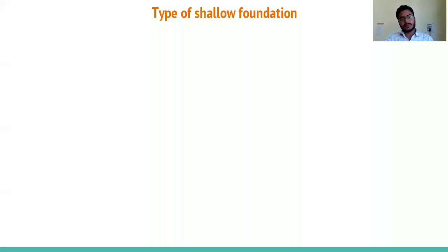What is pressure? Force by area. If you are increasing the area, automatically the pressure will reduce. So by doing this process, we can keep a lesser value of contact pressure as compared to the bearing capacity of soil, so the structure can be safe.